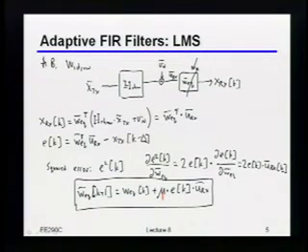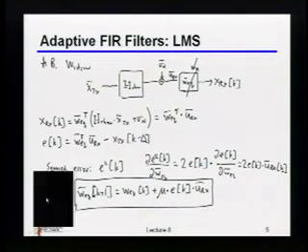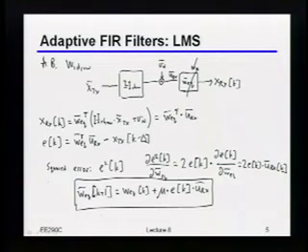Okay, so by the way, if you do this, what will your equalizer coefficients converge to? What type of equalizer is this? Yeah? ZFE? So there were only two options, and unfortunately you got the wrong one. Turns out this is actually an MMSE. I'll come back a little later and explain why, but this converges to the MMSE solution.